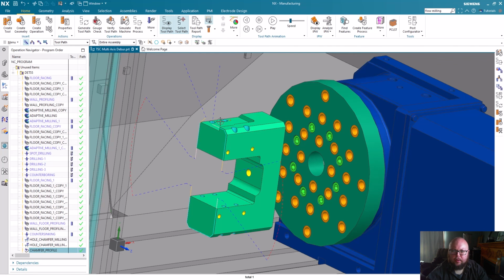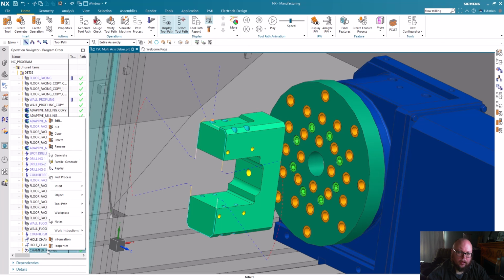So nothing really happened in my toolpath. I didn't change the toolpath whatsoever. The motions inside of NX are exactly the same. But what I changed by setting that linear tolerance is how the post-processor is going to interpret the motions and the various events it finds. And it's actually going to linearize the motions when A is moving here into smaller segments.